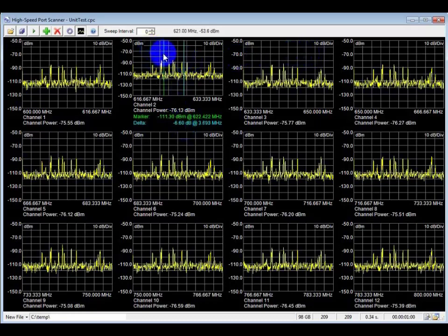I can also move the marker if I'm moving the mouse with the left mouse button. So I see those red crosshairs, and I click the control key, then the marker jumps to the position where the mouse was. And you see the delta marker maintained its relative position. So if I want the marker to be over here, I can pop that in right there. That gives me an easy way to position it with the mouse, or I can reposition. This is the best way for fine-tuning, just put the mouse over the labels and set them.